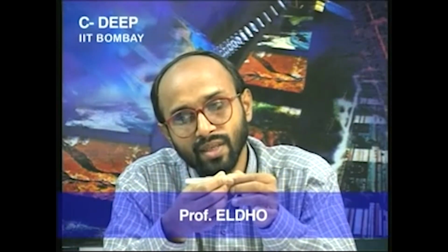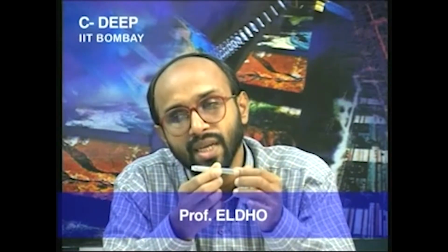Within the control volume, what happens with respect to time as far as the fluid inside is concerned is given by del by del t of the integral over the control volume of rho b dV. Then on the surface, what is coming into the system or going out of the system gives the integral over the control surface of rho b v dot n hat dA. This is the same as the above expression. So, this is the Reynolds transport theorem as described in this slide.